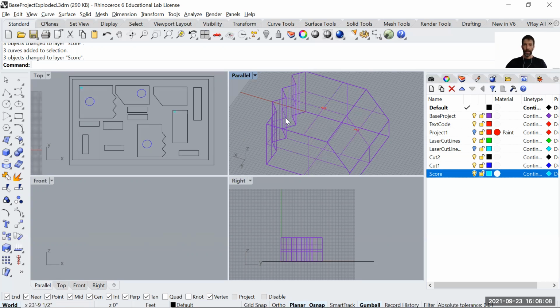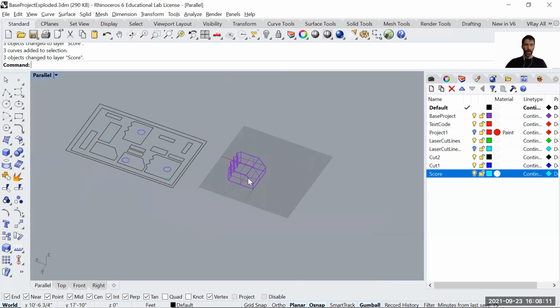So that's pretty much it. In summary, again, a process of the 3D model. It might have come from Revit, by the way. You explode the model that you have. You extract the curves. You make sure you add codes in the 3D model. And each of those curves that you extract from the model, you need to rotate them and place them on the C-plane and organize them in a template that you can request from the manager of your laser cutting, whoever that person is at the moment. The manager will give you a template.